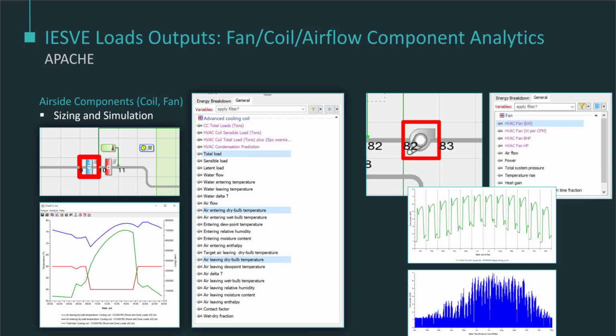So just to speak to that one really quickly, this little green chart here, or this chart with the green line on it, that is a design day load calculation. I know that because I can see it's 12 design day calculations. So in other words, January doesn't line up with February. Well, of course it doesn't, because they're different calculations, just have to be shown on the same chart. And that's what we use for design day calculations.